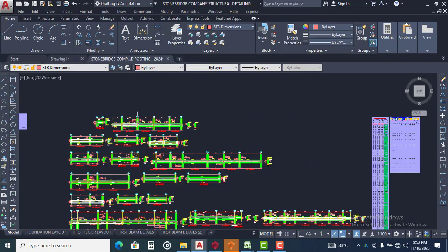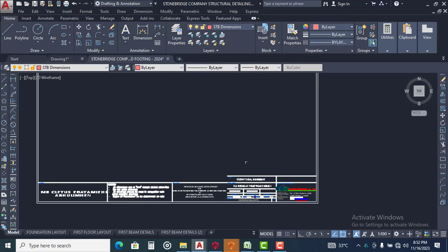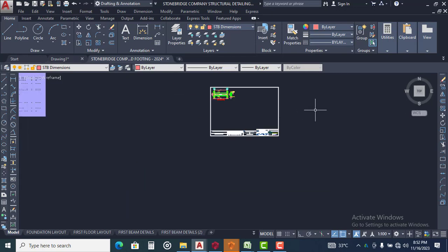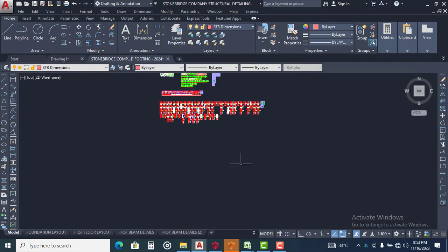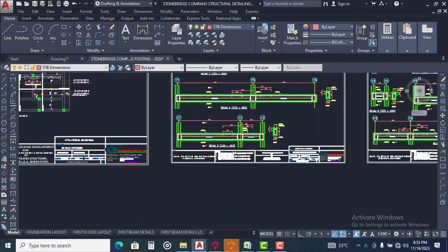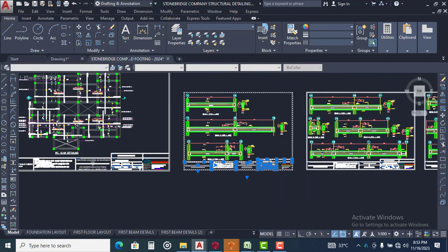But if you are copying your own company title sheet into this place here, I advise, sorry, I didn't copy this very well because there's a small mismatch here, so I'll quickly take this off and then go back here and copy back the particular size for beams. So if you are copying your own company template into this place, make sure you scale it to the exact size for these beams so that your drawings can be printed perfectly and accurately, to scale.